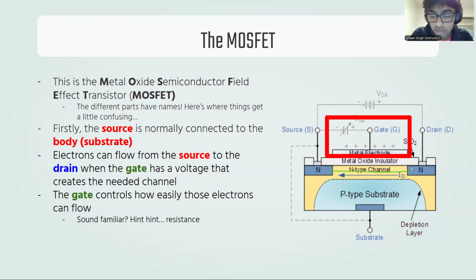And if you think about it, this gate is actually really tiny. Like I said earlier, since electrons are the minority carrier in this p-type body, the channel is super, super tiny. And so there's only so much current that we can push through here. If I apply a super big voltage VDS, it's trying to push so much current through just a tiny tube. It's not going to explode. Nothing bad is going to happen.